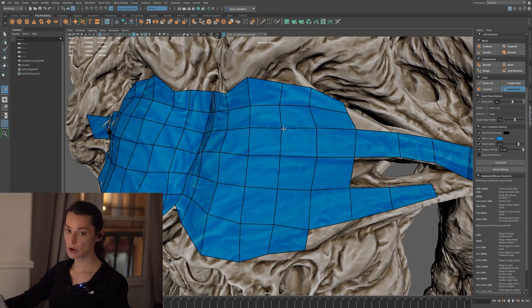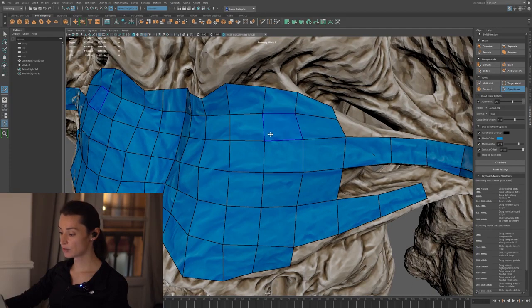And the other thing we haven't talked about is using the multi-cut tool. So sometimes you actually want to start to split, either add a bunch of triangles or split edges in a different way, okay? And when you're in Quadra mode, if you hold down Control-Shift on your keyboard and you do a right-click, you can see here that by holding down Control-Shift and right-click, I have the marking menu that appears. And if I do a movement towards the top, I'm going to get into multi-cut tool mode.